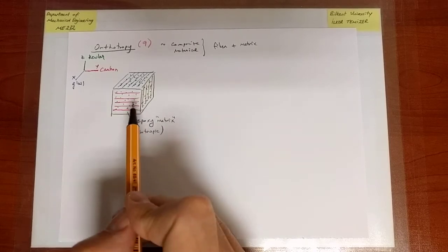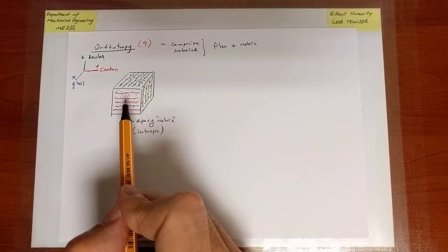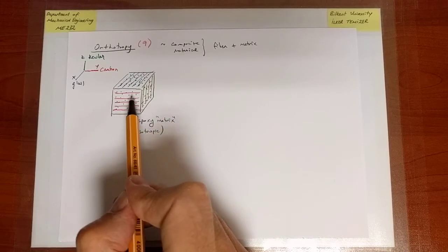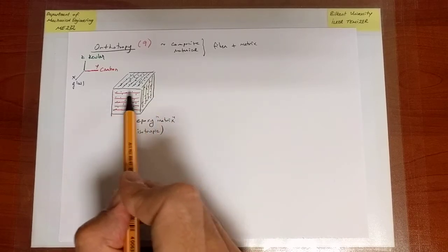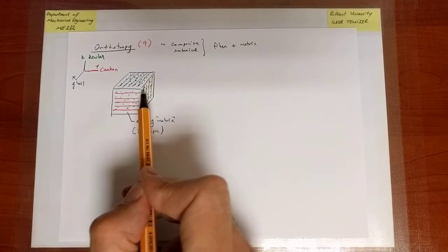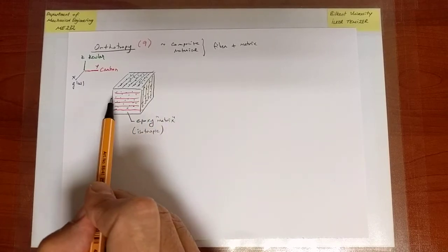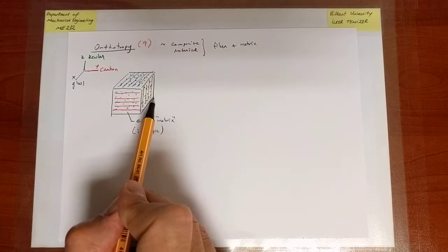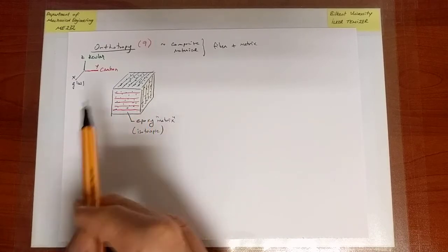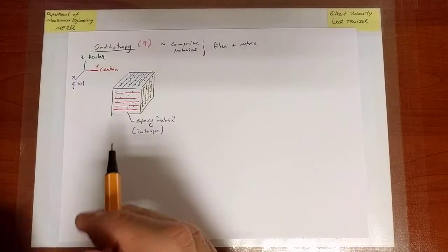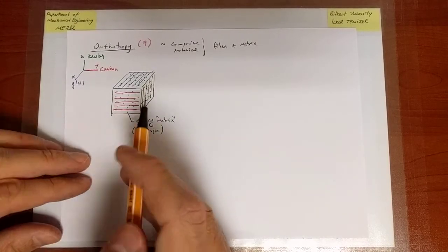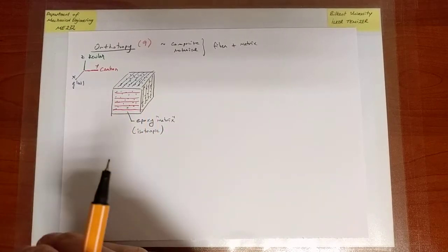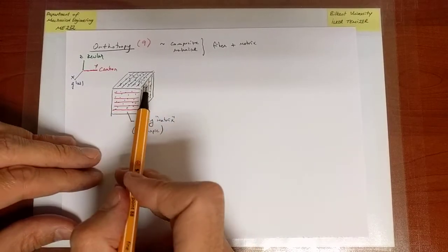And as you cannot put 100%, but less than it, the amount you put will influence how much closer you get to the modulus of, say, carbon fiber. When you put more and more carbon fibers, the more you put, you approach the modulus of the carbon fiber along that direction, but you cannot put 100%, so the amount you put does influence the result. The final result is neither the modulus of epoxy nor the modulus of the carbon fiber. That we should keep in mind.